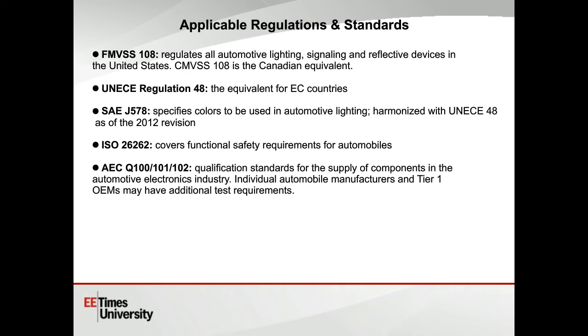A couple of standards that cover LEDs in particular from the SAE. The SAE J1889 first came out in 1988 and has been revised periodically since then. That one covers LED use in general, and SAE J2650, which dates back to 2005, applies specifically to LEDs used as illumination devices. In other words, LED headlamps.